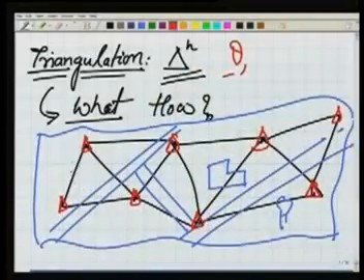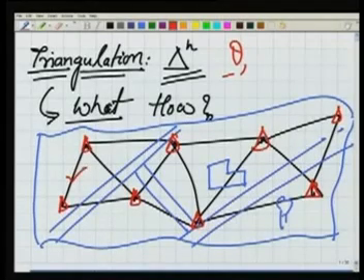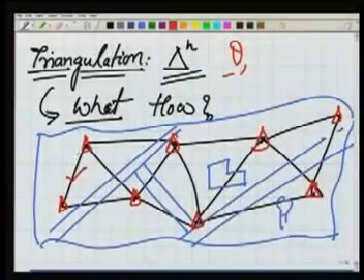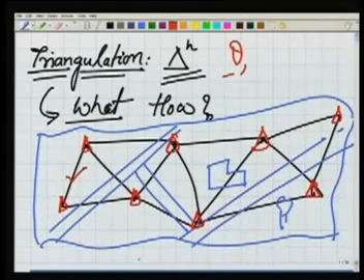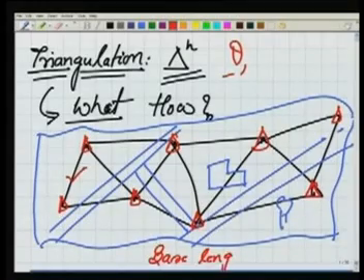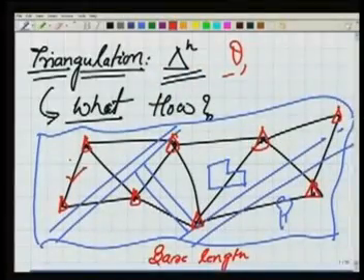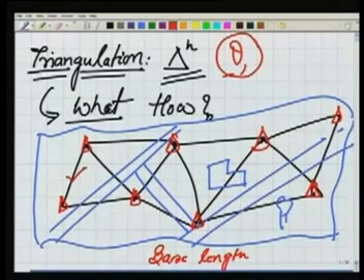and we want to have some method of measuring only one length here. What I mean, now in this I measure one length very accurately using some method. This method could be the chain, this method could be the invar or whatever. So this length which we are measuring here is called the base length. I write it here, or base measurement. So we are putting all our efforts in order to measure this base length accurately. Then later on, because we have a theodolite with us, using this theodolite we measure all the angles.